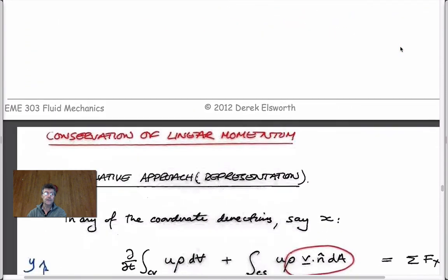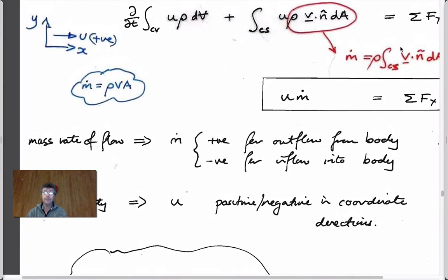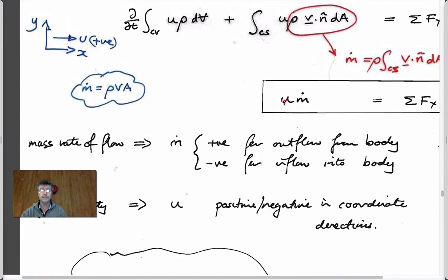When we deal with conservation of momentum, then we have to perhaps write this so that this term here is really, this is relatively important, right? To be able to include this. If it's static, then this term just drops out, and this is just the velocity relative to an observer. This is V static. And so it's important to be able to deal with this. So remember the sign convention, mass flow rates, we've used uppercase M, are always positive out. Velocities, which we've used for these, are always positive in the coordinate directions.